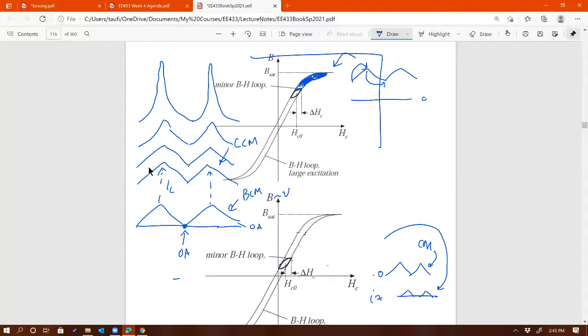And of course, that's dangerous, right? Because this magnetic component is typically connected in series with a switching device. So that switching device is also seeing that current. In the process, it will break that switching device, it will melt the MOSFET because of that big current. So that's why you want to stay away from it, and why it's important for us to know ISAT.